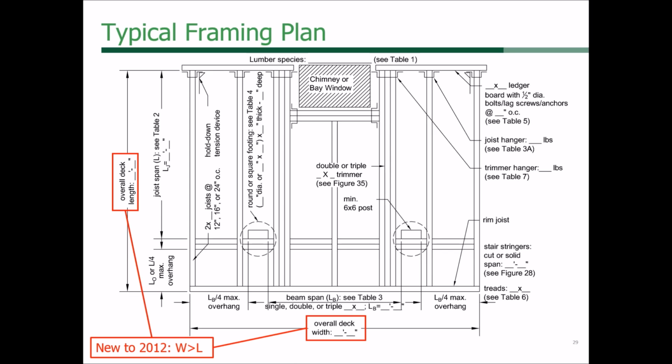And if you've only got horizontal lumber, you can look in our special design provisions for wind and seismic and see that it's one of the weaker shear walls. It's not that great. Even if you did diagonal decking instead of horizontal, you'd be better off. So it's just a matter of making sure that the load can get back to the house.